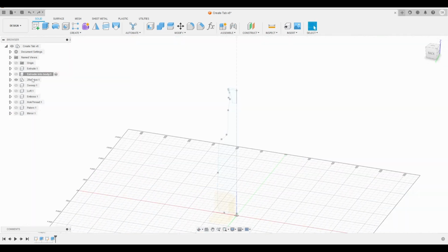See? Next up, we have the revolve tool. Basically, what the revolve does is that it grabs a 2D sketch and makes it spin around while giving it volume. So let's say, for example, we have a 2D sketch of a bottle and its cork. In this case, we'll make the 2D sketch of a bottle spin while giving it volume.